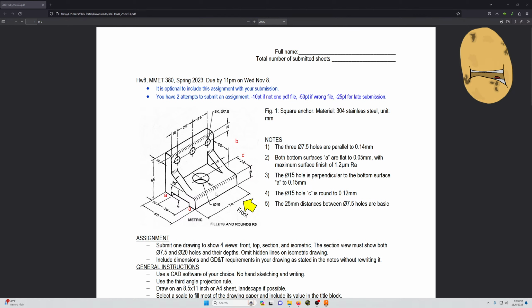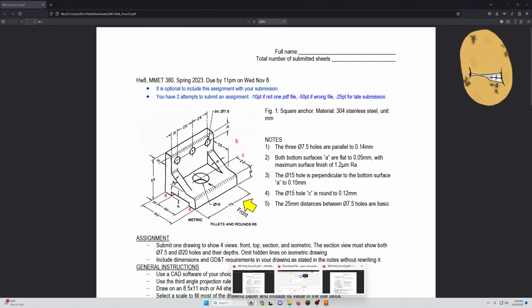So these center lines tell you that they are not only just a perfect circle, but exactly that it is in center of this entire thing. So we're gonna go with the assumption that it is in the middle of 70. So 70 divided by 2 is 35. So it is 22 high and 35 to the middle. 22 and 35. Those are the numbers.